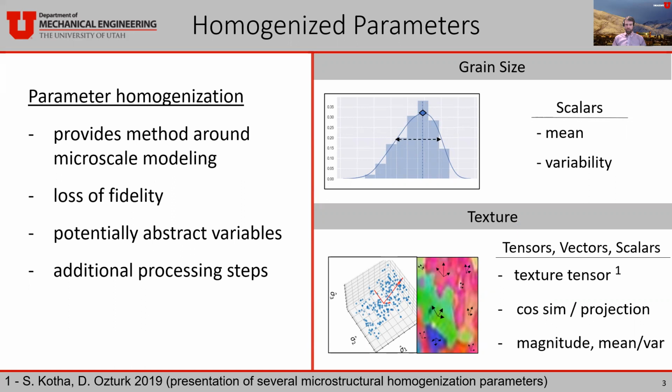The weights are the grain size, and the eigenvalues of this tensor correspond to the intensity of the texture in 3 orthogonal directions, and those directions are given by the corresponding eigenvectors of the texture tensor. The eigenvectors also align with the material axis of symmetry for that specimen.